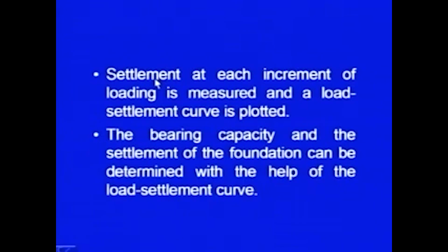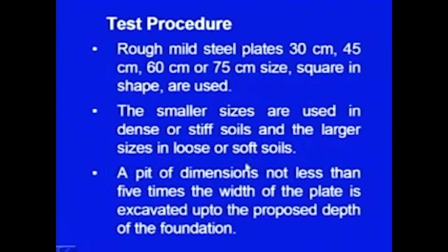We will be measuring the settlements using some dial gauges, and those settlements for every incremental load we will be measuring, and then a load settlement curve will be obtained. Then the bearing capacity and the settlement of the foundation can be determined with the help of this load settlement curve, that we shall discuss how we do it.